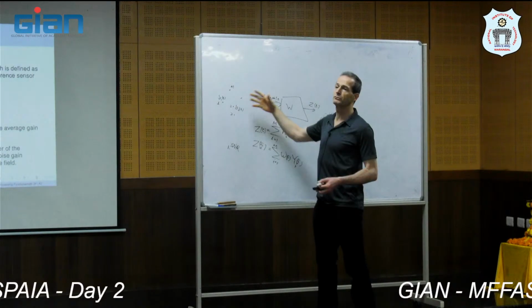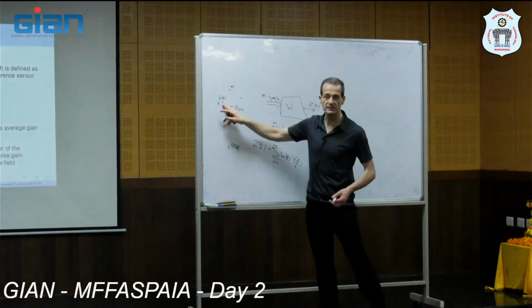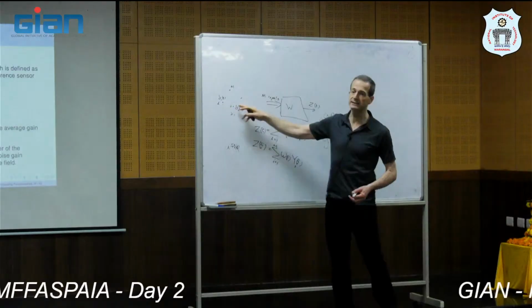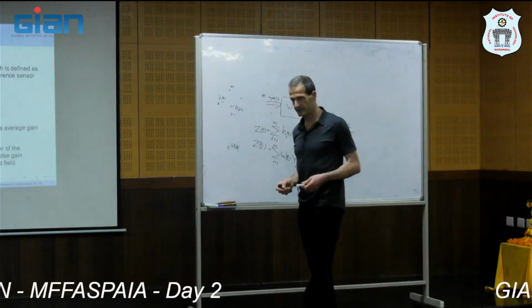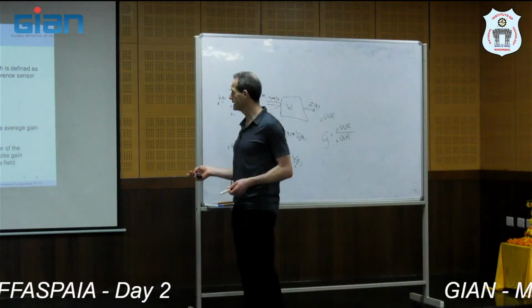This is the gain of the desired signal. We also have what the noise is here compared to the noise in a single sensor. This is the gain of the undesired, the gain of the noise. So this ratio is the same as output SNR divided by input SNR. We want this to be as high as possible, so we have more gain in SNR. This is called array gain.